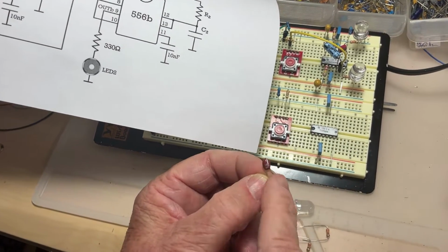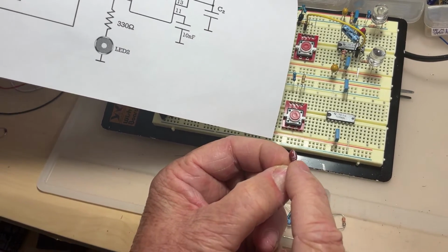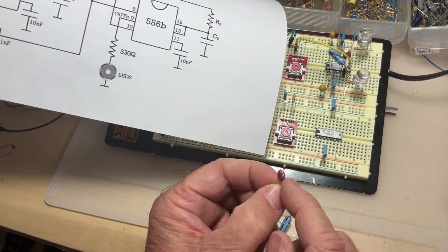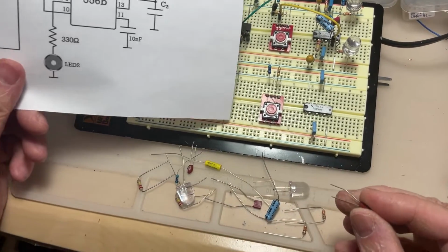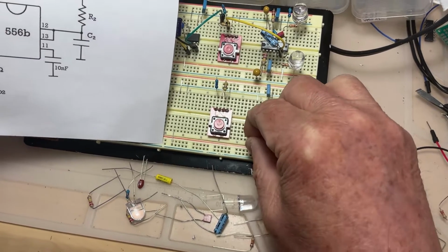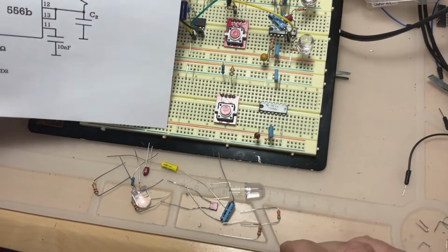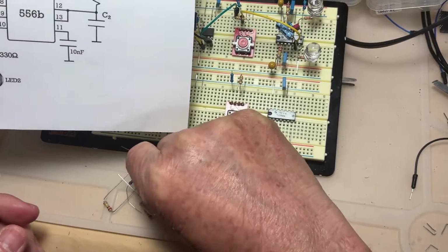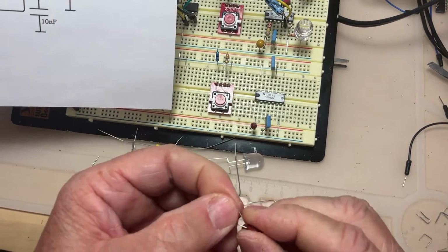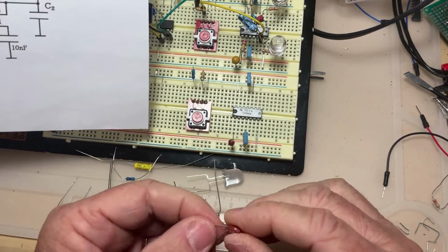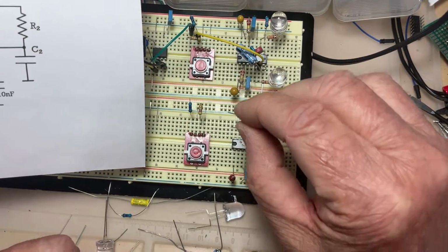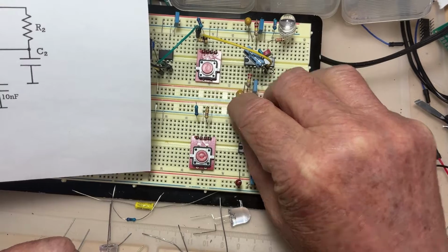So you have to notice there is a white line which is marking the positive, and the positive is going to the pin 1. So it's going to the pin 1, to the ground. And the same thing goes about the second capacitor. If I pick it up, this one is going between the pins 12 or 13 to the ground, from here to here.